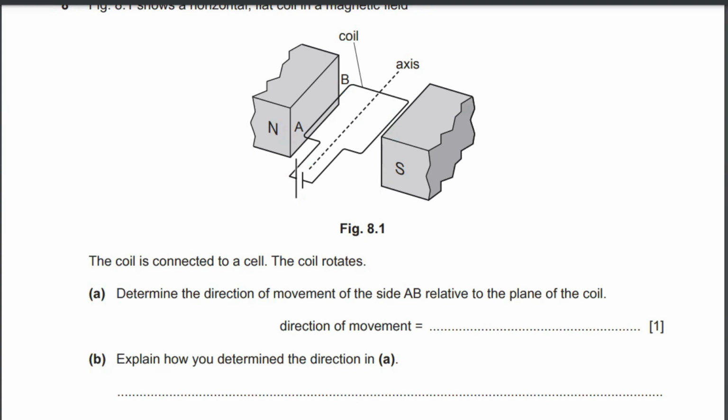So Fleming's left hand rule has 3 parts to it. So one is the x-axis. Let's say this is the middle finger, which is for current, and the y-axis for force, and the z-axis for the magnetic field. So the thumb will be the force, the index finger will be the magnetic field, and the current would be the middle finger.